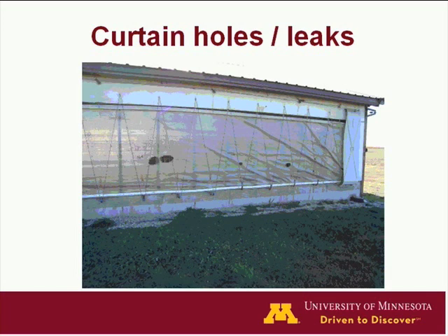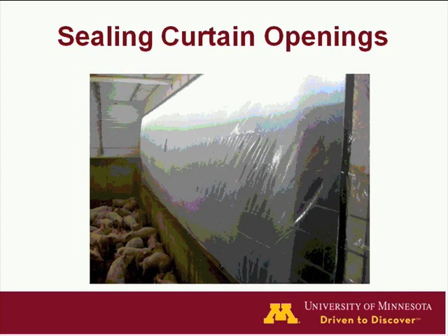It is important to make sure that we don't have a lot of leaks in these curtains, or that they're tight, because leakage can really increase the air exchange in the barn, or uncontrolled air exchange, that subsequently can cool things off, and we have to make up that heat with heaters.